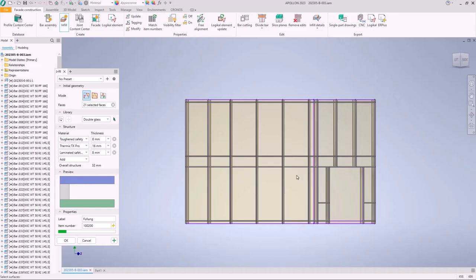the correct clamping thickness and the insertion into the profiles are defined in the bar assemblies. With the Logikal bar assemblies, it's defined automatically because it's system dependent. And if you create your own bar assembly, you can assign these parameters directly in the component function of APOLLON if you create a new bar assembly. So this is also possible.